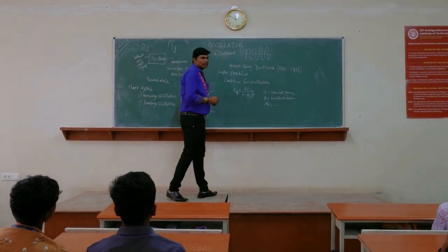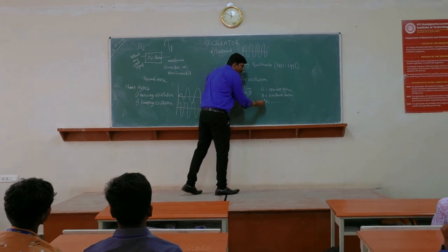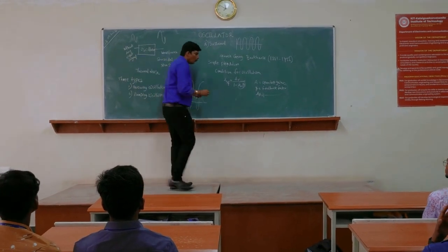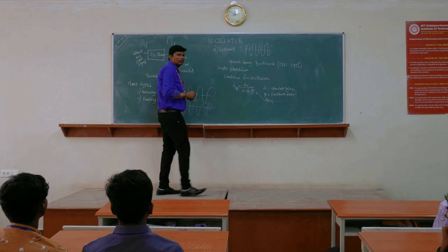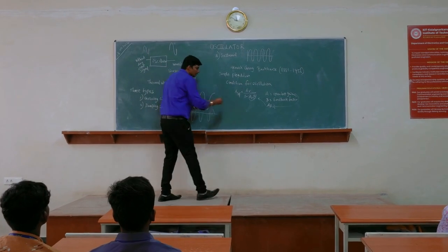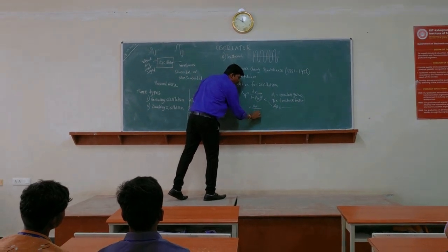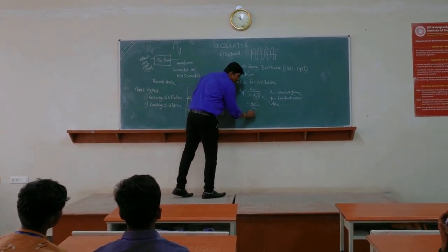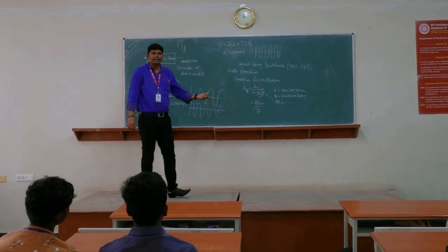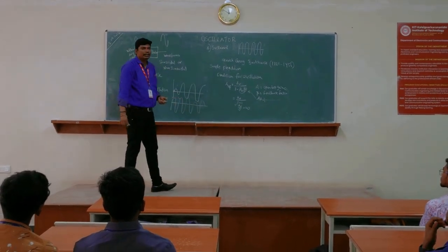If Aβ maintains a value of 1, what happens to this equation? You know that, right? A and β together equal 1. The voltage gain without feedback divided by 1 minus 1, that becomes 0, is it right? Anything divided by 0 is nothing but infinity.